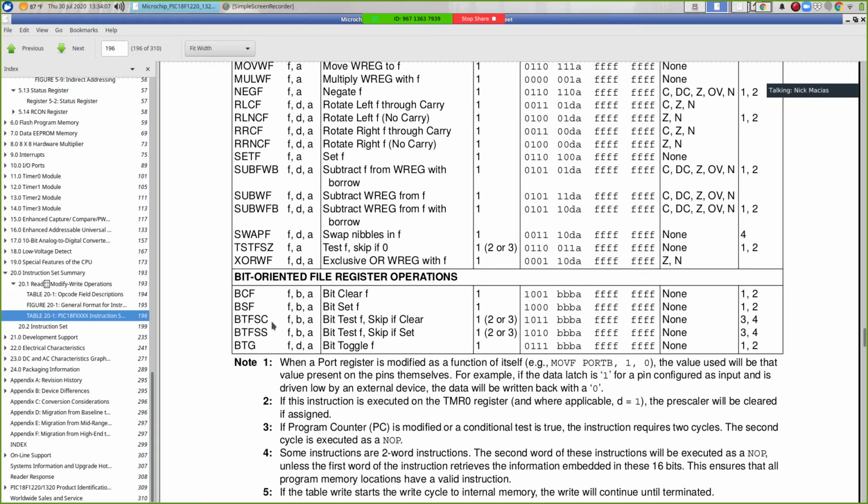You don't need to use these, right? I could take my register, I could construct a bit mask, I could AND those fields together to pull off that one bit, and I could say branch if it's 0 somewhere, and that lets me do something conditionally based on a single bit. But inevitably you'll encounter these, if not in this course, somewhere else, so I want you to see these. And they're classic features of reduced instruction set architectures like ARMs and PICs, because they're a tighter way to code branches. Fewer instructions and faster execution.